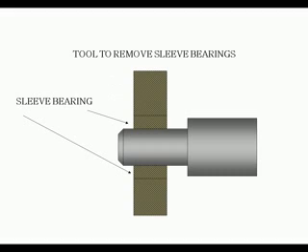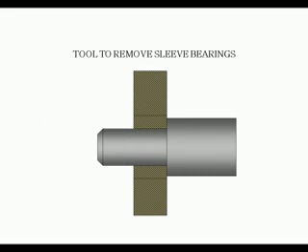Mechanical motor problems are the most common problems involving the bearings or drive connections. Bearing failure could be tight or worn bearings, lack of lubrication, excessive grit in the bearings, and might have over-tightened belts. They're not often repaired by the field technician. It involves disassembling the motor on a bench and replacing bearings and making sure everything's lined back up. Most often you will not replace these.